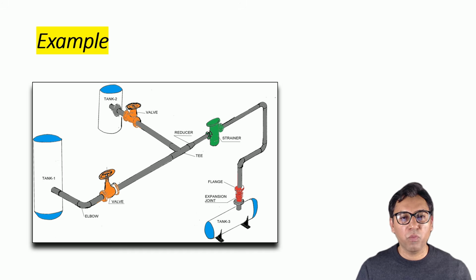Now let's use an expansion joint in our example and see how our piping system looks. You can see here we have used one expansion joint which is a bellow type. This will give flexibility to our piping, and especially will manage load on the tank nozzle. Now we will add some piping instruments to know about the fluid inside the pipe.